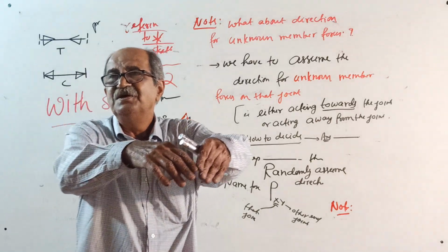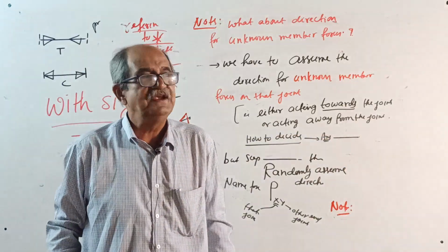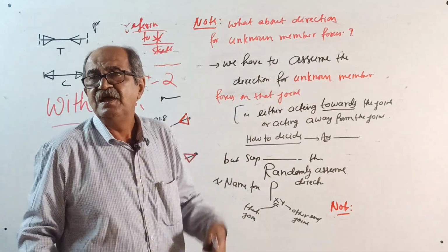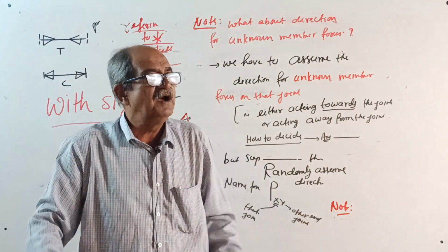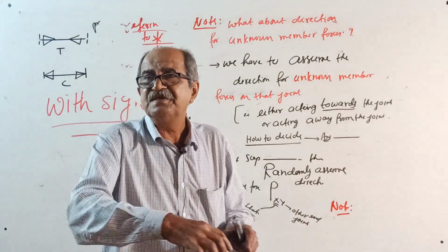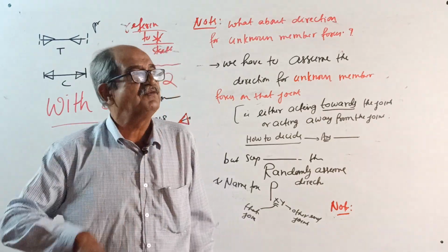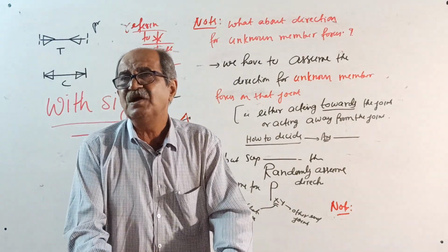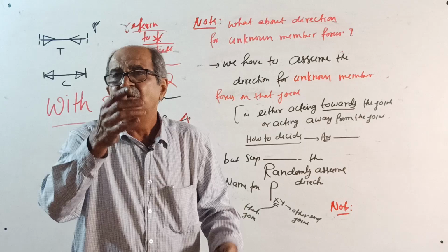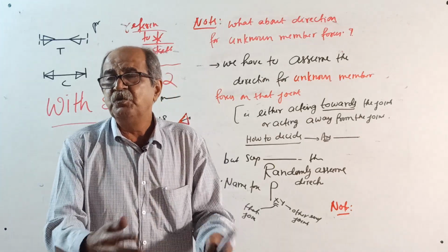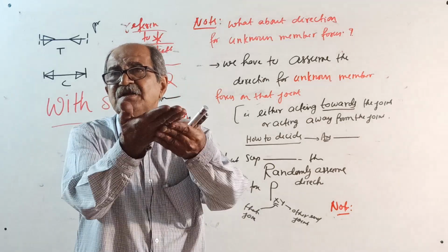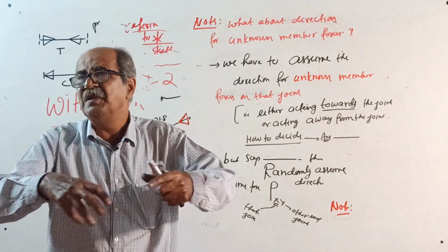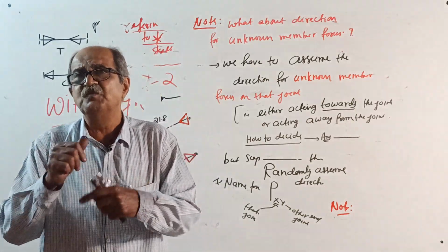As soon as everything is ready for laying the foundation, he will take a photograph. You can see, my site was like this earlier, empty. Once he places the bed concrete, one more photograph. Place the footing reinforcement, one more photograph. Then after footing reinforcement, place the column reinforcement, and photograph. Put the concrete, let the column come to some height, one more photograph. Then, as it comes to ground level, plinth beam layout, whatever preparation is being done, one more photograph.